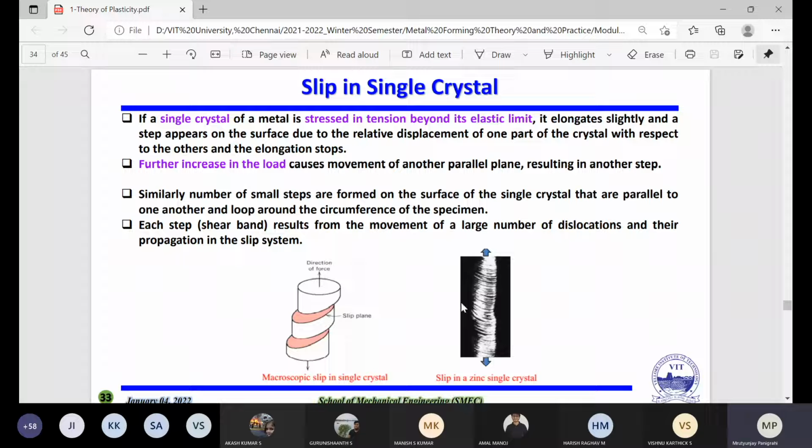So the moment you do this, in a typical zinc single crystal, you will find this kind of structure. Because when we are stretching anything, we just observe that plastic deformation happens. But when you go toward a microscopic test or any kind of high resolution microscope, then only we understand how it actually looks. A schematic diagram is very easy, you can just predict and tell, but how it originally looks in the single crystal, you have to find like this.